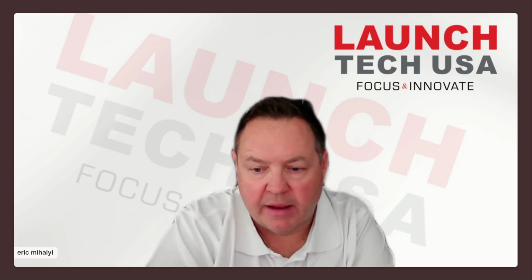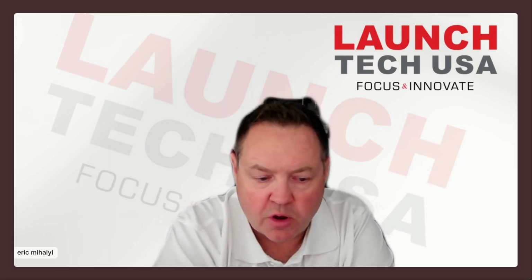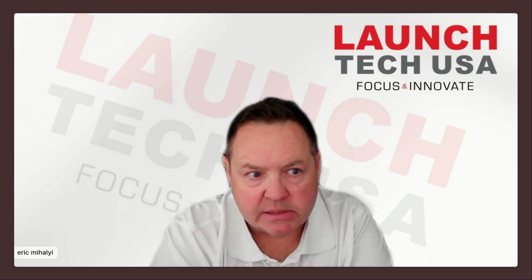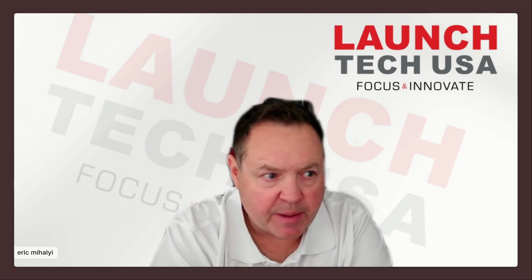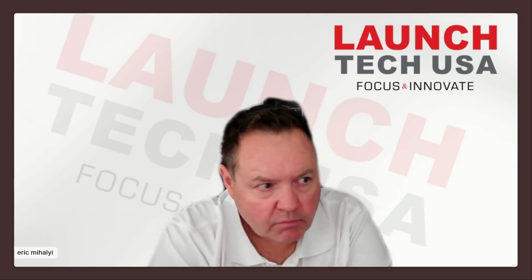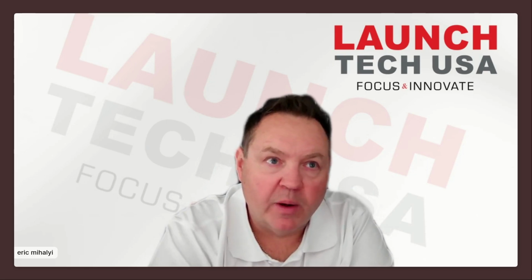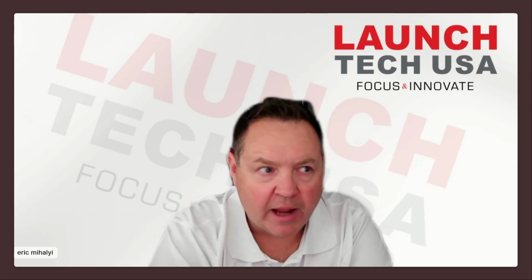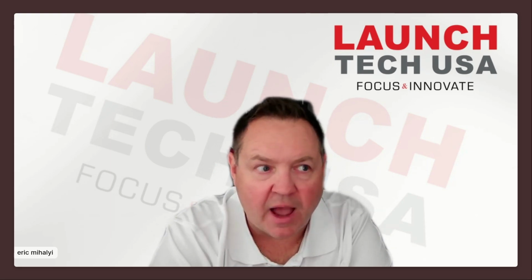And TSBs, I really can't stress enough. I listen to a lot of our level 2 calls, and sometimes I take some of these calls, and sometimes I feel bad for people because they've maybe wasted so much time. We had a gentleman, about maybe 2 months ago, having issues with the TPMS tool, and no matter what he did, he said, I've replaced the sensor 3 times, I've done this, and no matter what, I can put 150 psi in it or make it flat, and it still reads 19 psi.